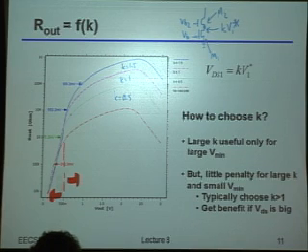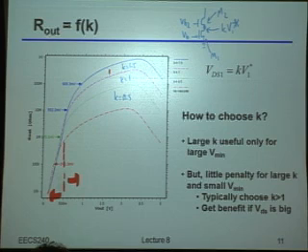What you can start to see is that pretty much no matter what voltage I'm at, the output impedance you get from something where you've biased that middle node higher is always higher. Now, in some regions it's basically the same, but it still says that if there's ever a situation where you get a higher output voltage, then the output impedance of the cascode structure with the high middle bias will be higher.